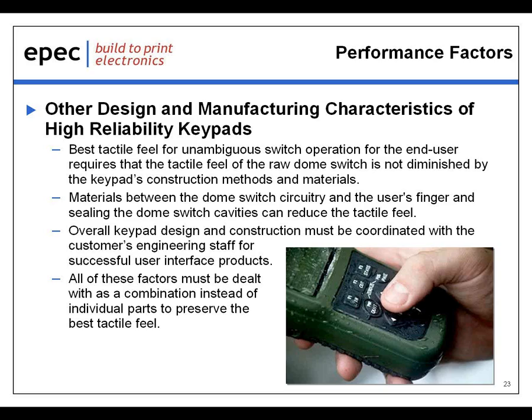Materials between the switch dome circuitry and the user's finger and sealing of the switch dome cavities can all reduce tactile feel. For the keypad to work as intended, the overall keypad design and construction must be coordinated with the customer's engineering staff for a successful user interface product. Now, all of these factors must be dealt with as a combination instead of individual parts to preserve the best tactile feel. Keep in mind that the keypad is an assembly, not just a collection of loose components. All the parts of the keypad must work together for a successful design.